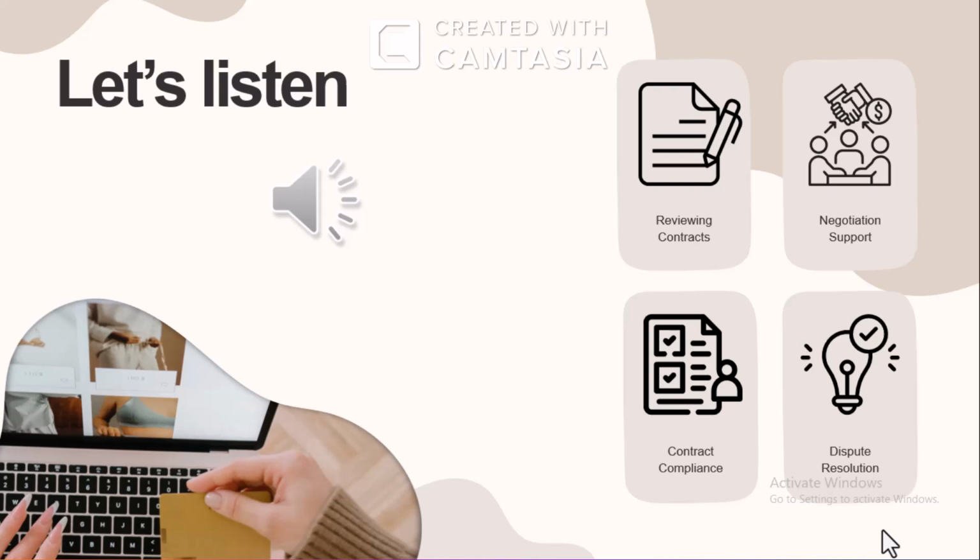Hi, we had an issue with the SMT machine in line 3, station 2. What was the problem? First, there was a vacuum pressure low error. We found a loose vacuum hose and fixed it. Good. Anything else? Then we got a feeder sensor error. The sensor lens was dirty, and the infrared beam was blocked by dust. Nice work troubleshooting. Anything else? The pick and place head wasn't picking up components properly. We found a nozzle clog and cleaned it. That's excellent. Next time, check the vacuum pressure settings and sensor calibration regularly. Will do. And make sure to report issues clearly from now on.